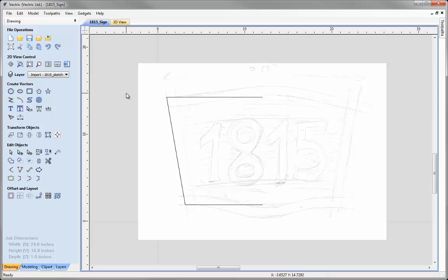So when we've made a few more edits, in a few minutes we'll go ahead and make an incremental save to this, and that allows us to keep track of all the different versions of the file as we progress through the design. The next new feature I want to look at is mirror node editing. If we select the vector we've created here and hit N on the keyboard to go into node editing, I'm just going to hover over this span and hit B to turn that into a Bezier, hit B to turn this bottom one into a Bezier, so we've got these curves.